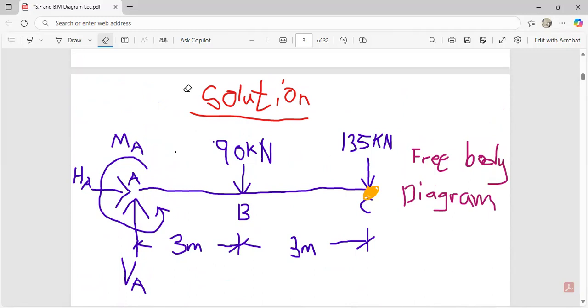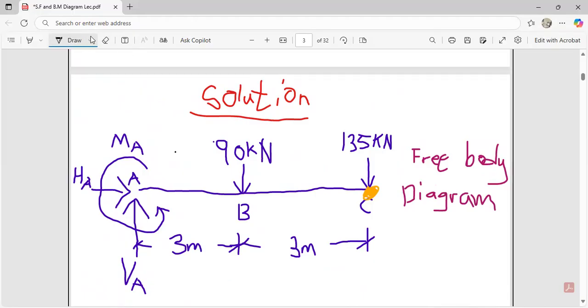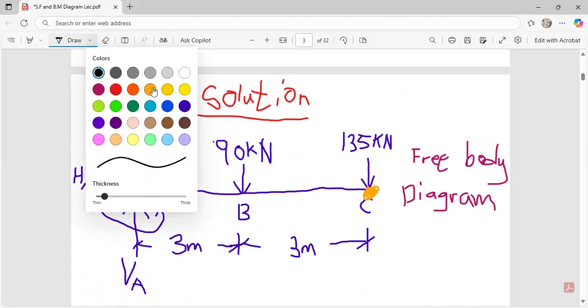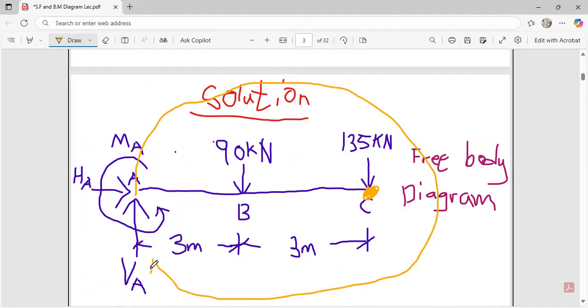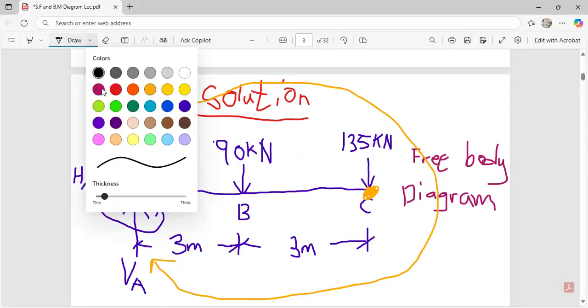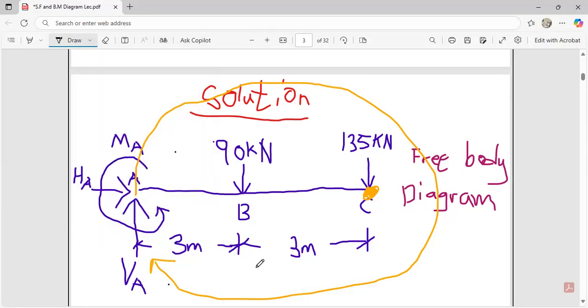So that is it. So if we are standing over here and we are going to take our moment, it means that we are going to stand at C and open our compass to VA. So if you follow the direction at which VA is taking, you realize that VA is going to be taking a clockwise moment, and that is going to make it become negative. But this time, which question do we ask ourselves? The VA has covered a distance of 6 meters.